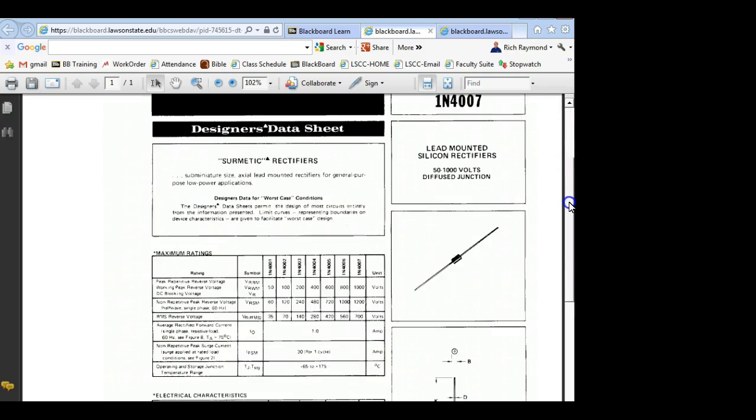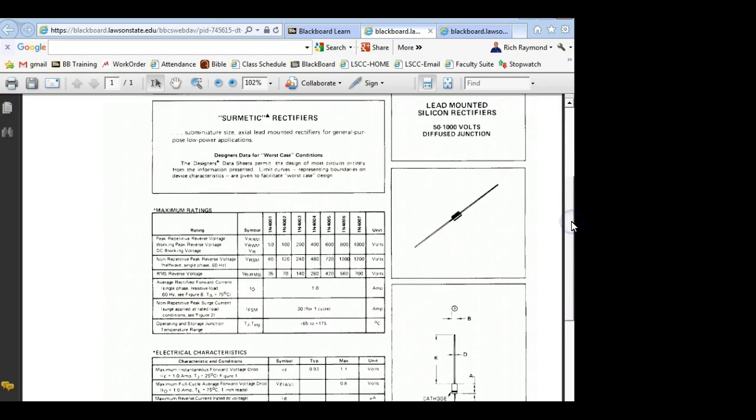So data sheets for diodes are fairly easy to understand. But on this diode, a rectifier diode, now on the switching diode, you could get it in microseconds, right? You understand? This guy says for 1 full cycle, which means we could maintain 30 amps on this guy for 60 cycles for about 16 milliseconds. And we're only going to do it for a half cycle, or less than a half cycle, so we shouldn't have a problem when we start charging this thing. It's just that when we originally charge it.